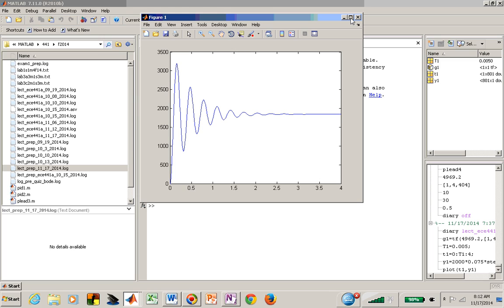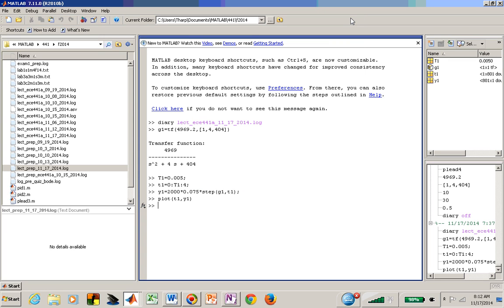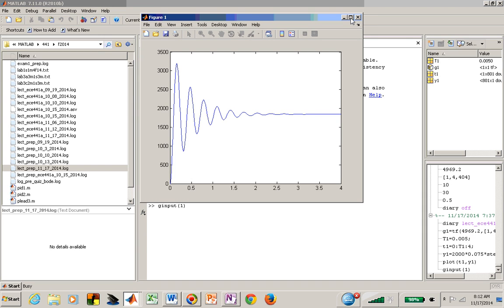This is one of the nice things with Matlab. You can say, give me one data point, go graphically, so get a graphical input. Who knows if I'm going to be able to do this very effectively with this mouse, but now I have crosshairs, and I could actually go and find that peak.